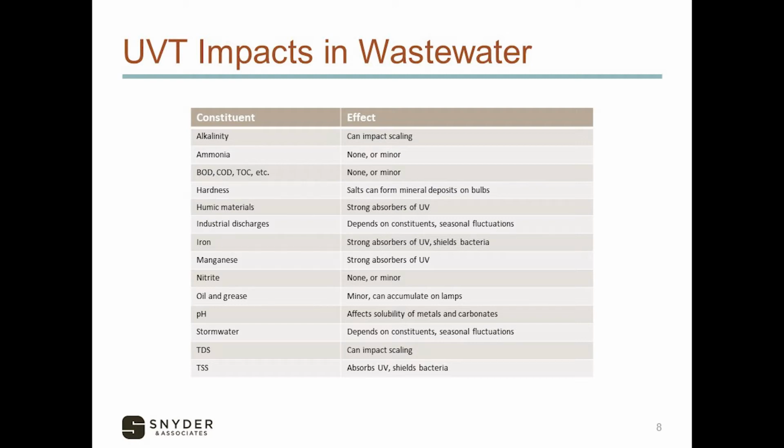So calcium, magnesium, any kind of salts, they will oftentimes provide the ability to put really strong deposits on your UV quartz tubes, especially when you elevate the temperature. Guess what happens inside those tubes when we are running UV light? Elevated temperatures. There's a lot of things that can affect transmittance, and it's something you've got to keep your eye on when selecting a process.